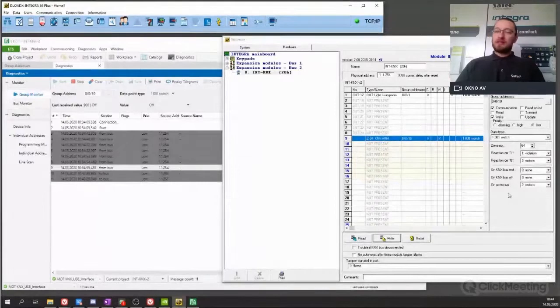So right now we know how to send information from INTEGRA panel to KNX to control something, for example, giving you a status of the door, windows, PIR, room occupancy, or any kind of alarm like fire alarm, like flood detection, etc. We know how to receive information from KNX to INTEGRA panel to be able to arm, disarm system, change the status, do anything inside INTEGRA panel, for example, control some kind of outputs in INTEGRA, or for example, to open garage door that is connected to INTEGRA panel, etc.